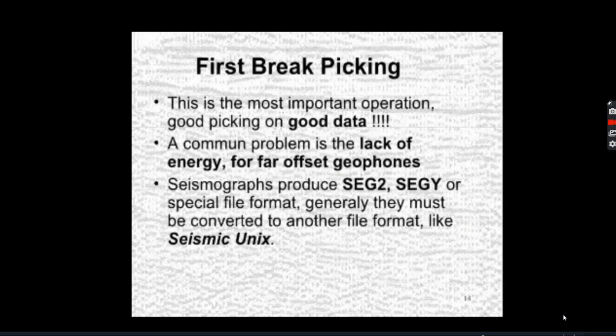First break picking. This is the most important operation. Good picking needs good data. A common problem is the lack of energy for far offset geophones. Seismographs produce SEG2, SEGY, or special file formats. Generally, they must be converted into another file format like Seismic Unix.